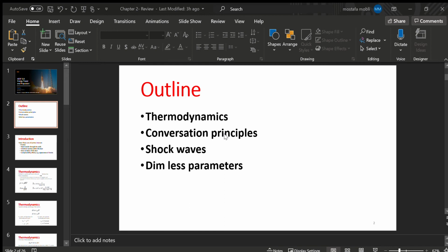We have the definition of gamma. You just replace it there. Replace the definitions of Cp, the relationships we have here, for the definition of gamma. You come up with this: gamma equals 1 over Cv over R. So just play with it a little bit, some mathematical play. You can find the definition of heat capacity based on gamma and the gas constant: Cp is gamma over gamma minus 1 multiplied by R, and Cv is 1 over gamma minus 1 multiplied by R.